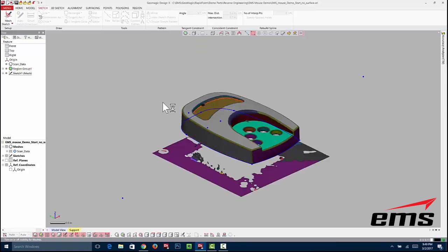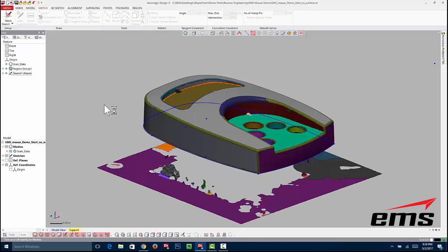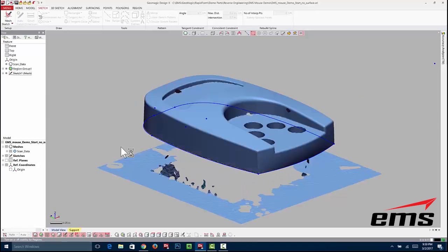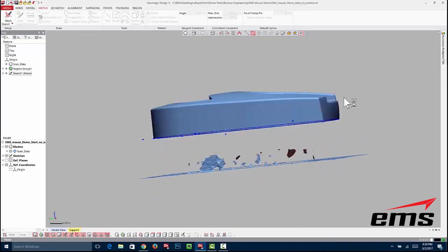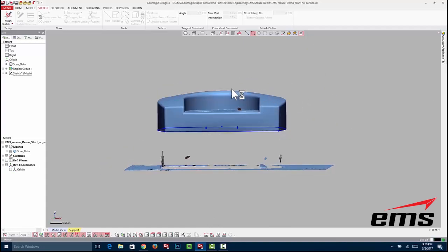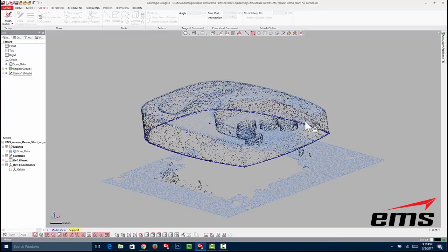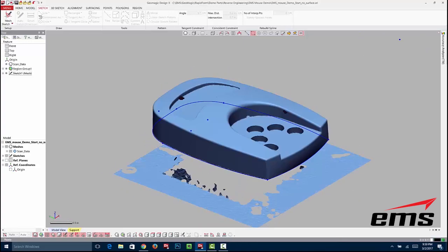Now, what I'm going to show next is really one of the really nice things that is more difficult to do without a scanner or without this software. So if you notice, this surface along the top is curved this way, and it's curved this way. So I'd call this a compound surface. Now, trying to measure that manually, with micrometers and manual tools, trying to build this surface would be extremely difficult, and one of the reasons why you want to use 3D scanning.